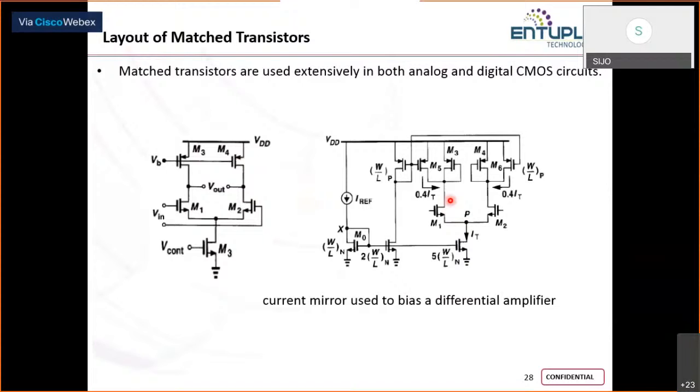That is a PMOS device. In the same figure, on the left and right side, from M1 to M3 and M2 to M4, the wires we realize for the connection between the drains and the output should also be matched in terms of length. Why it should be matched is because we are doing all the analysis taking it for granted that it is a differential signal and an identical pair of devices on both halves.